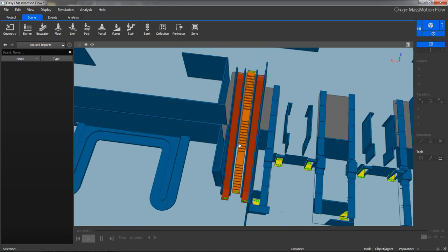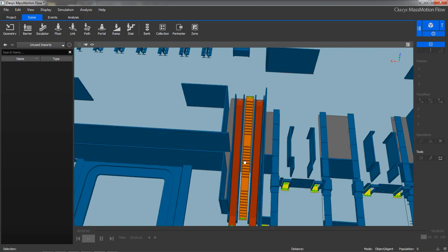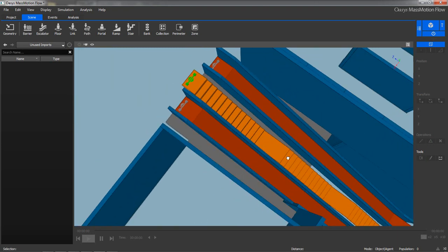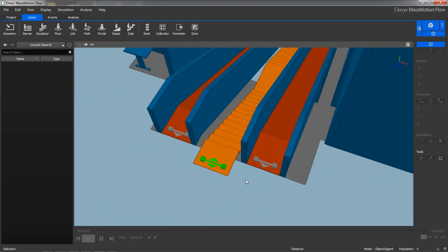And then there's another thing which has happened in here which is a bit more subtle. The way that the escalator geometry was defined, it comes up and meets the floor geometry, butts it almost perfectly, which is almost correct but not quite. We can see from the stair here, which is fully formed and well formed, that to have this active green color on the end of these escalators, we're actually going to need to make them overlap a little bit with the floor.